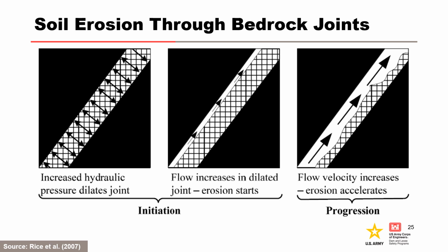Increased water pressure developed due to the seepage barrier will reduce the effective stress on the joint and has the potential to dilate the joint and initiate seepage pathways through the bedrock that were previously not significant. The increased gradient along the joint also increases the potential for erosion of joint infilling.